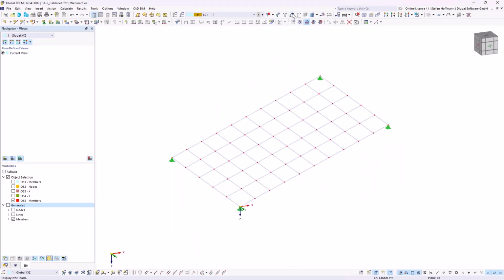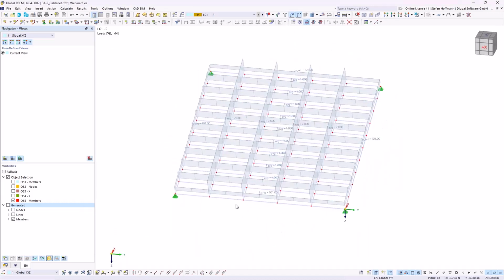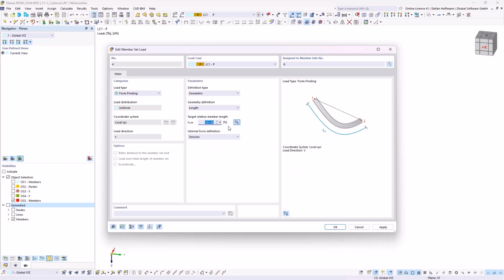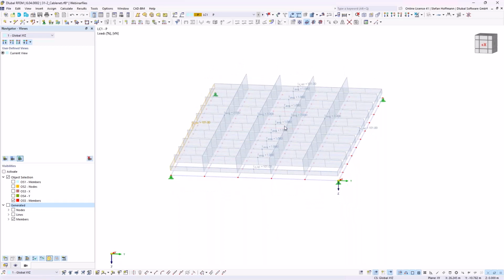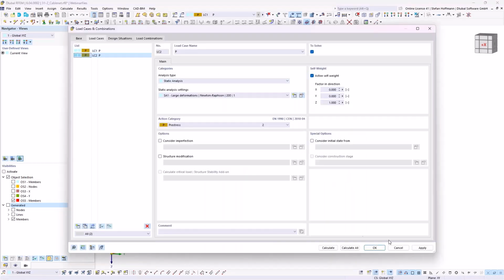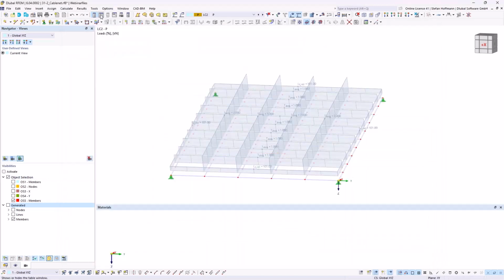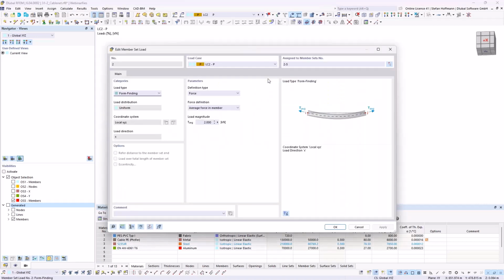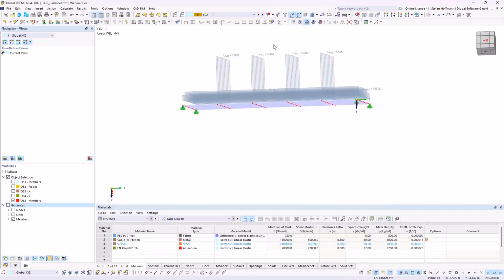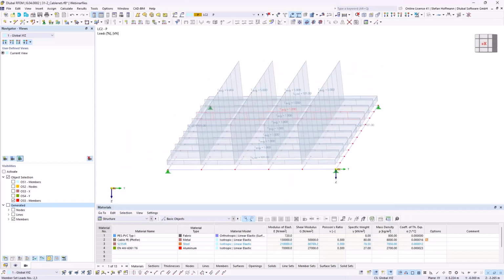So by doing this, we are able to define member set loads. And I have now defined them this way, that I have a geometric member set load for 101% of relative member length for my rectangle. And in the inner member forces, I have chosen 2 kilonewton into this direction, and into the Y direction, I have chosen 1. So remember, if you want to compare different pre-stresses in one file, you just simply have to copy this load case, for example. Then you can activate the table, or also just mark multiple forces over here in order to go in and quickly change it from 2 to 5. That's most likely all that has to be done.